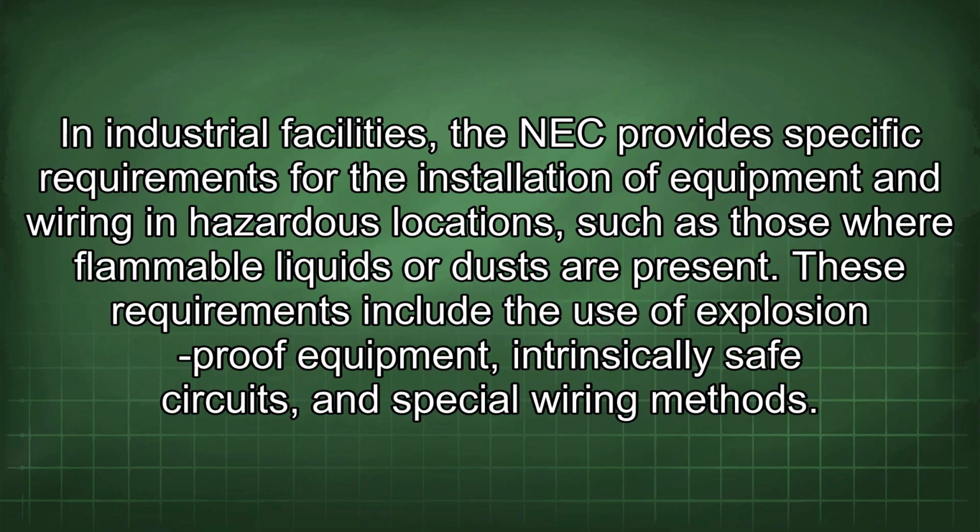In industrial facilities, the NEC provides specific requirements for the installation of equipment and wiring in hazardous locations, such as those where flammable liquids or dust are present. These requirements include the use of explosion-proof equipment, intrinsically safe circuits, and special wiring methods.